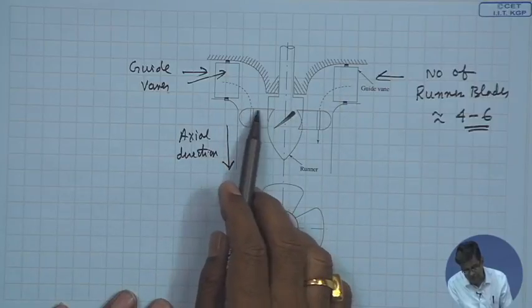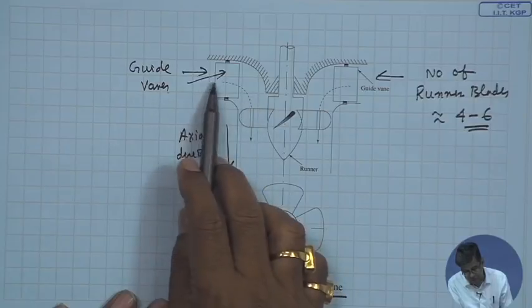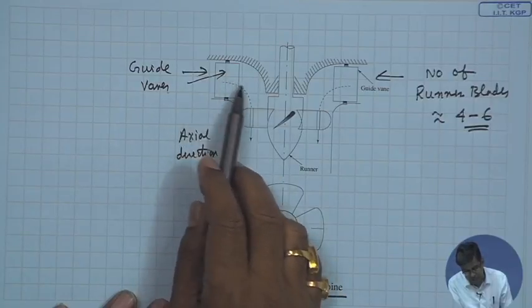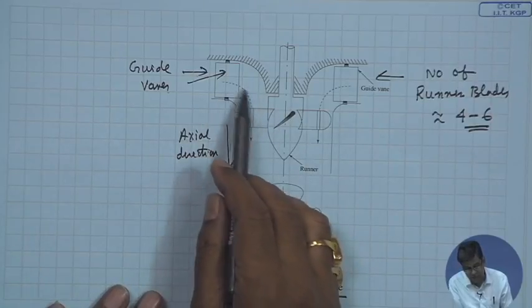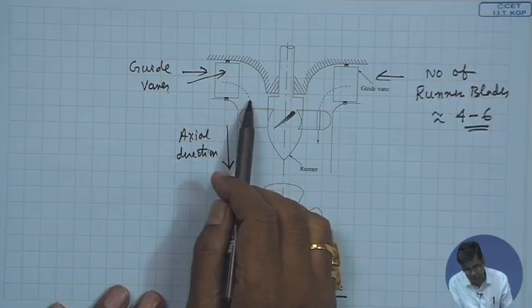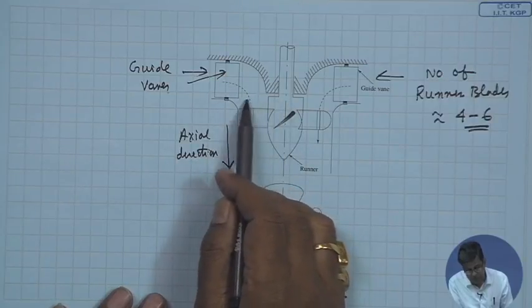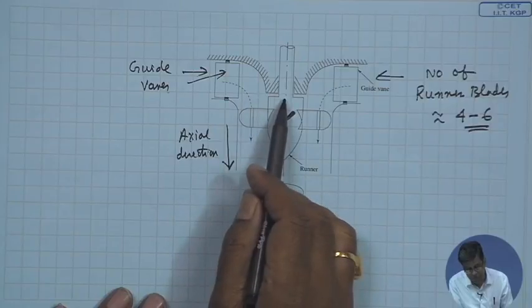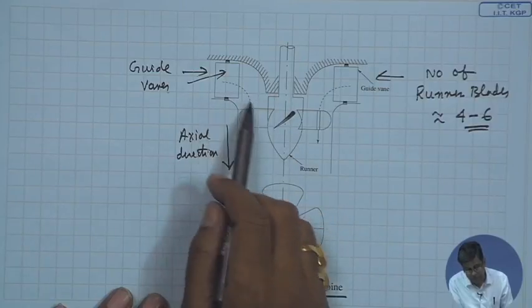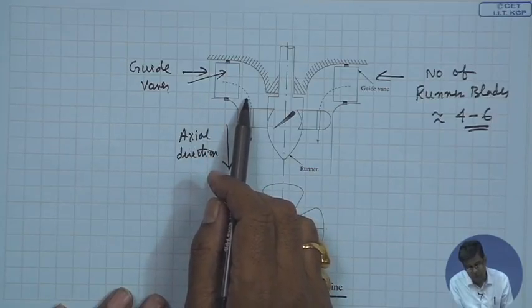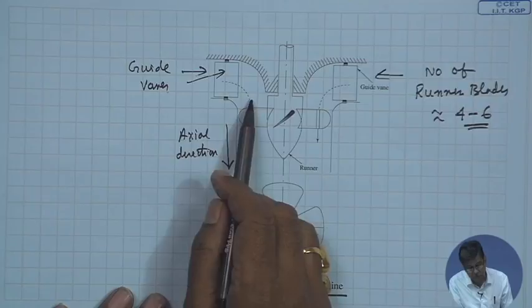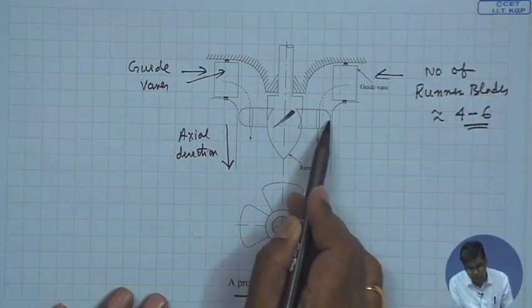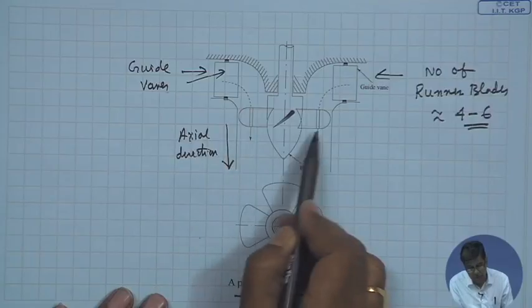as it reaches the turbine blade. This swirl in the static part, or the stator of the machine, can be considered as that of a free vortex flow if we discard the effect of viscosity, where the tangential velocity increases with a decrease in the radial location from the axis of rotation. That is the free vortex rule: the tangential velocity is inversely proportional to the radial distance from the axis of rotation. It can be approximated more closely with a free vortex rotation, but the rotational motion of the blade is solid body rotation, which is a forced vortex type.